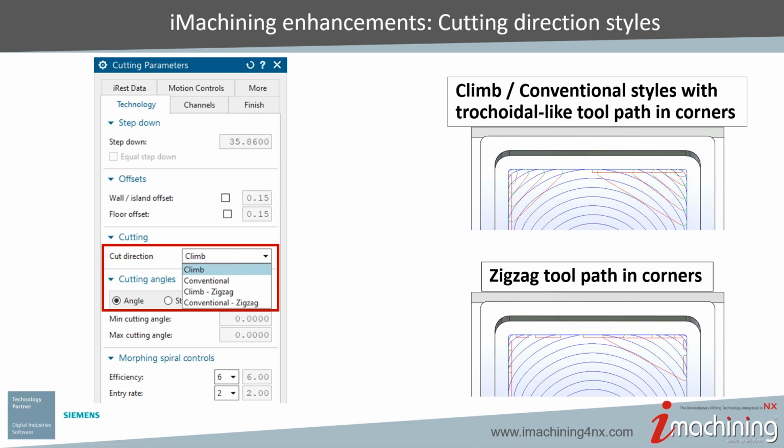And then we also have zigzag machining, which is useful if you have something like a really soft material. Look, I'm the type of person who still believes climb cutting is 99% what you want to do, but definitely we have customers, especially I'd say NX customers, with really big parts, especially aerospace parts, where you're doing long cuts and big horizontals, big machines and aluminum using pretty big cutters. And obviously, if you're using a 3/4 inch end mill in aluminum, you can climb and conventional cut. So the tool is going to accept it, especially when it's not some really long tool.